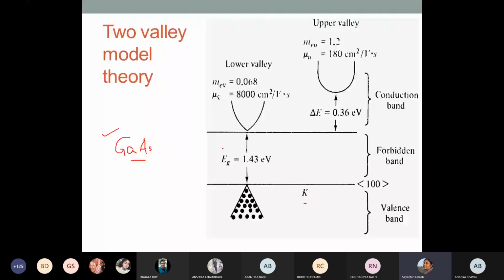Okay, but to understand this two-valley model, or the effectiveness of gallium arsenide for making a Gunn diode, we have to move beyond this. So conduction band minima and valence band maxima lie at the same value of K. But as I said, the conduction and valence bands are curvy, wavy lines in the EK diagram. These lines don't go just up. They vary like anything, and can finally result in several valleys and several hills.